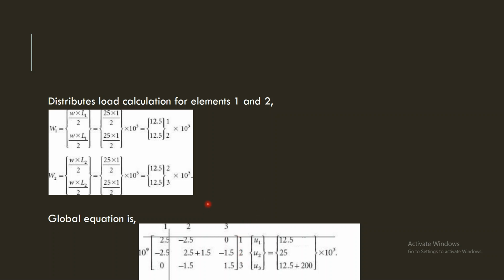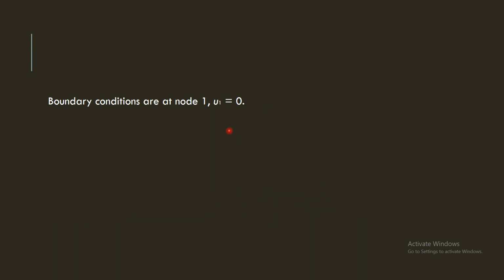maintaining the equation in terms of F equal to K u, already defined here. This is the K matrix, and this is the u matrix, that is equal to F. This is how you have to go for the K u format. That is the global equilibrium equation that I already showed here. Once you did this, the next part is applying the boundary conditions.